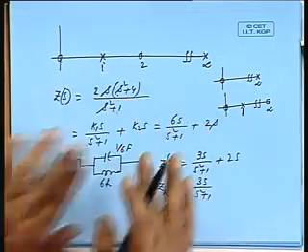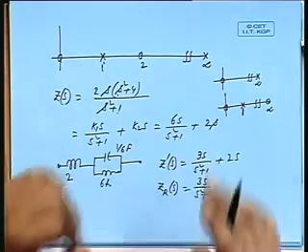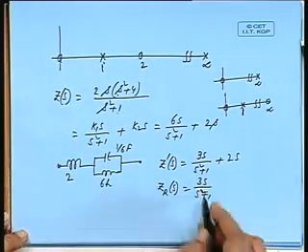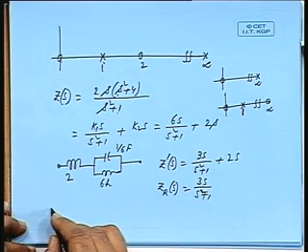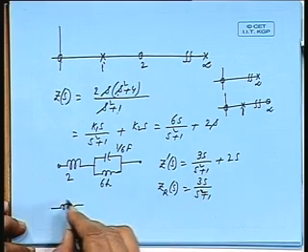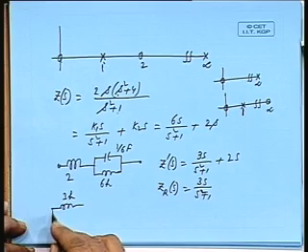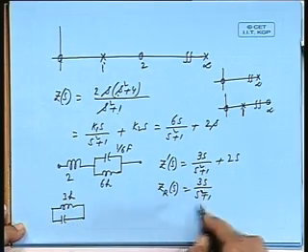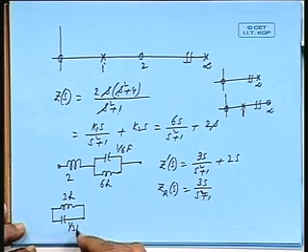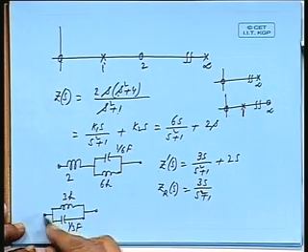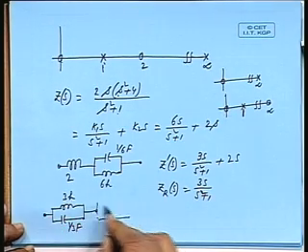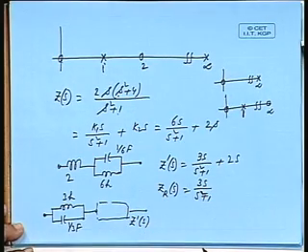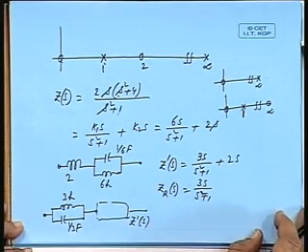That means 50% I have removed, 50% I have retained. So, if I remove 50% of this, means 3s by (s squared plus 1), I will have 3 Henry and 1/3 farad. Suppose I take out an element like this, whatever is left over is Z dash s, is it not?